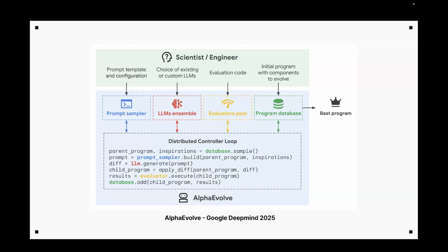So you can imagine having a bridge set up and then just saying, hey, Raven, try to come up with a better performing structure of my given bridge and Karamba simulation, and Raven can just go and try out 100 or 1,000 different bridges, always checking them against the Karamba simulation, and finding an even better performing bridge than you might have been able to come up with, just because it can search in a space that is validated by the Karamba bridge,